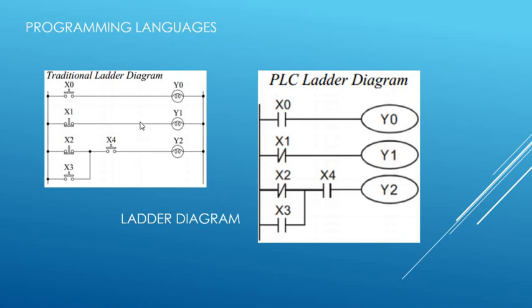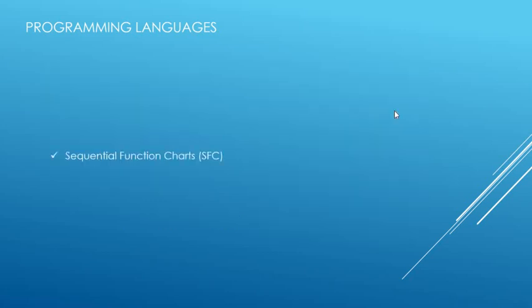But nowadays, if you look at all those three, TIA from Siemens, RSLogix from Rockwell, GX Works 2 from Mitsubishi, they use it like this. It's very similar. So you have normally open. This could be a limit switch, this could be a push button, this could be a flow meter, and so on. It doesn't really matter. Whatever type, you have a similar input: normally open, normally closed. And for the output coil, most of them use a kind of parenthesis. That's like a coil or the output.